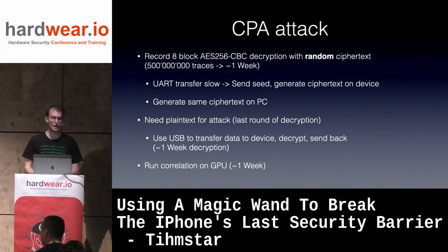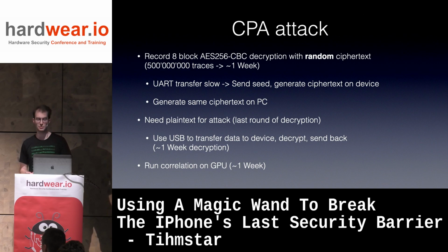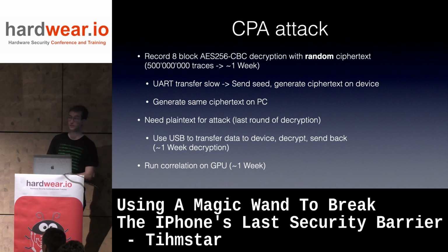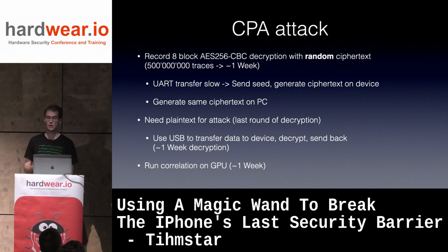For the actual attack, I recorded 8 blocks of AES-256 CBC decryption with random ciphertext. I recorded 500 million traces, which took me about a week. Transferring everything over UART is kind of slow. By the way, I used UART for communication because the scope was a Windows machine and getting UART to work was easier than the proprietary USB protocol, and it had other advantages. But basically,